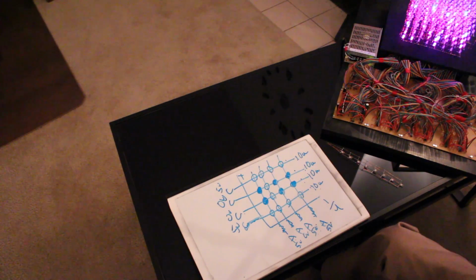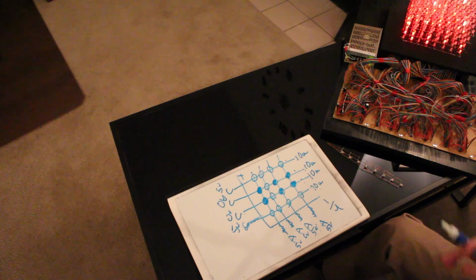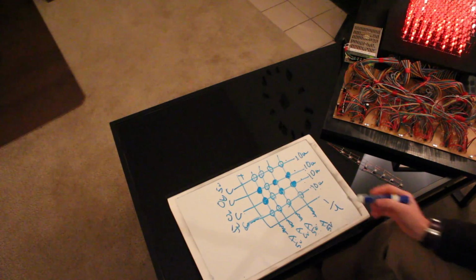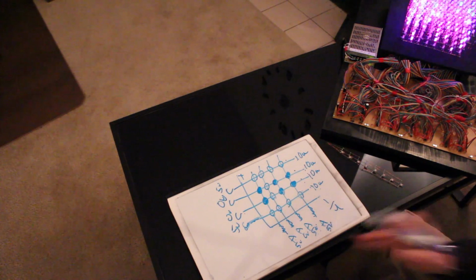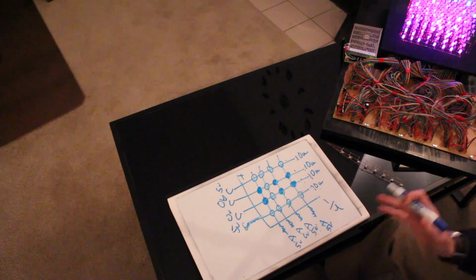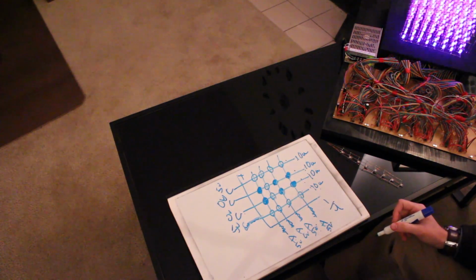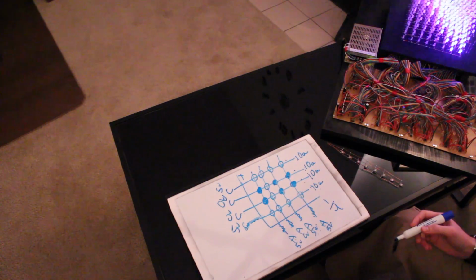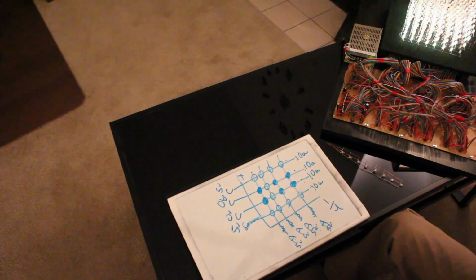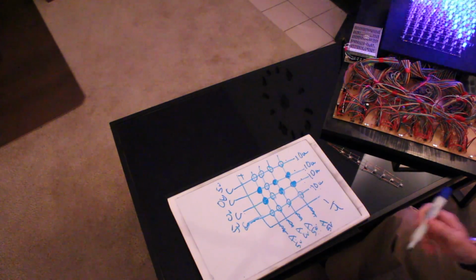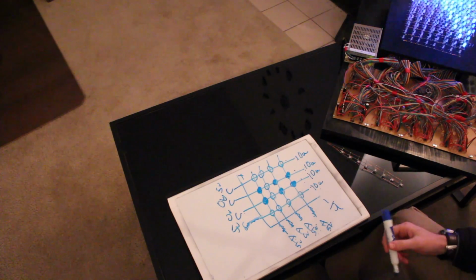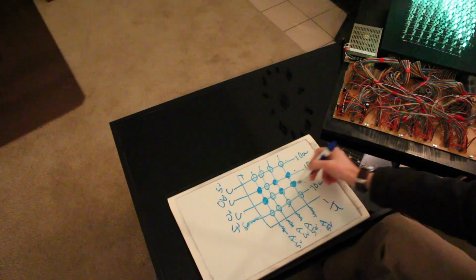Now, this is when things get a little confusing. We're controlling these LEDs. Each LED, right out of the gate, has its full-blown brightness at 1 out of 4, a 25% duty cycle. And yeah, we could play games with the current limiting resistor. But be careful with the current limiting resistor here. If you did lower that, what if your code freezes? What if you're stuck at a row?